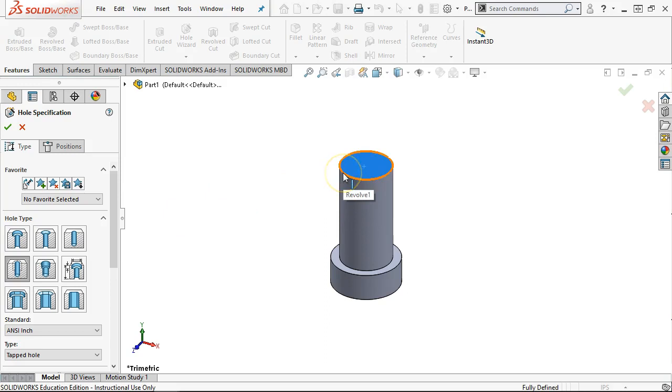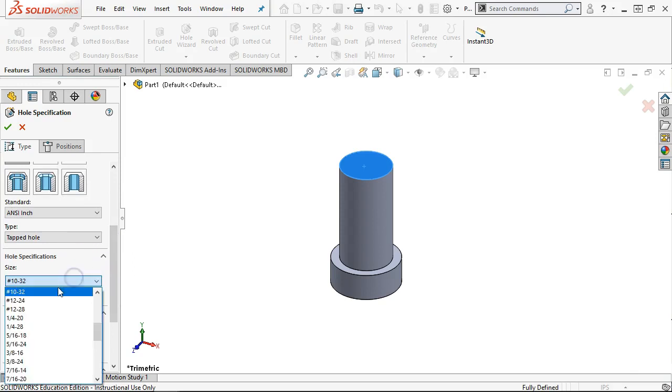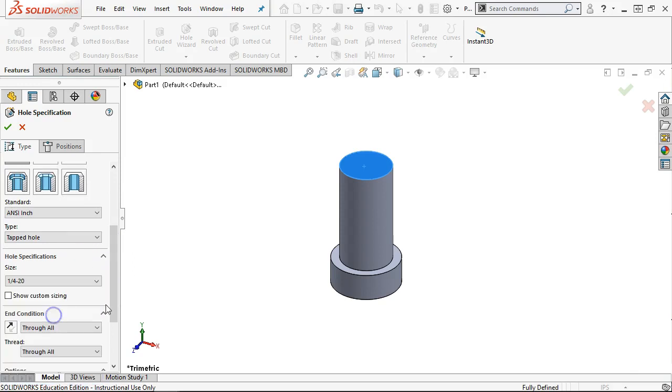What I don't want, and so thinking through that design process on the stack up side, I don't want this to crush. I don't want it to cinch down on the bearing if we have the tolerance that's not at the same relative scale to those spacers. All right, so I'm going to switch over to the tapped hole, and I'll make this a 1/4 right?